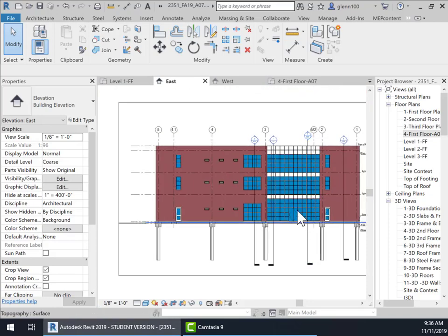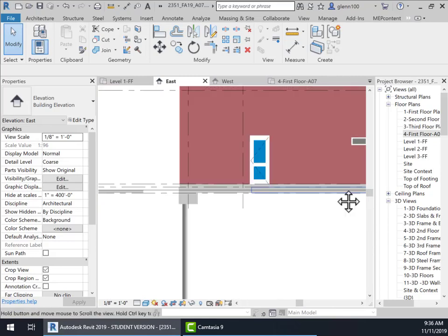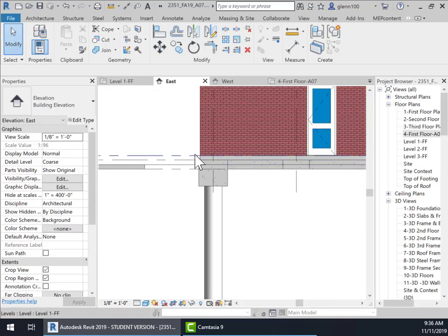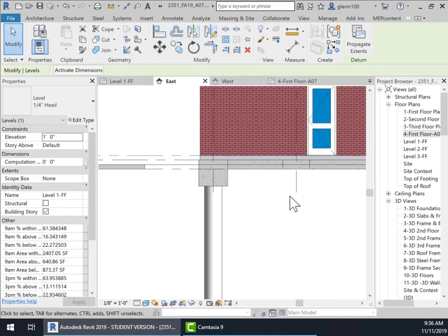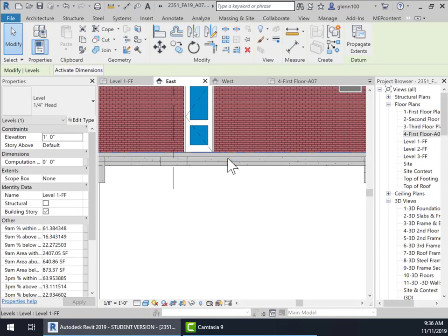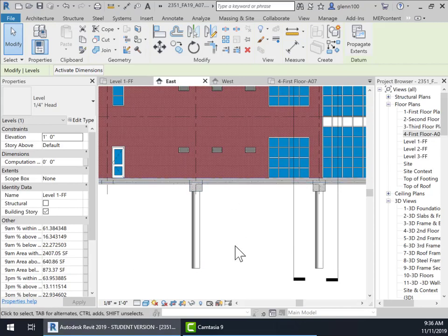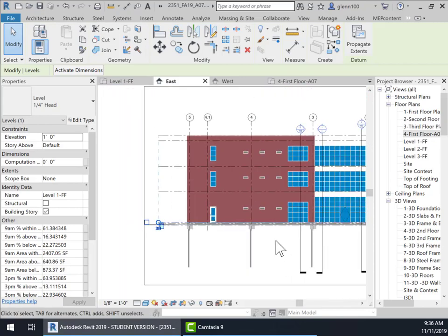We should have put one in here too, but we'll go ahead and put it in now. It's going to start at 6 inches below the finished floor. The finished floor is where our slab is, and we want the building pad to be the depth of the slab.